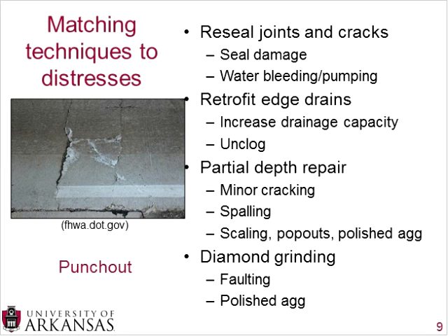And what can happen if you have those is the water bleeding and the pumping. Once those seals get damaged, water can go in and can come back out of those seals. And also material from the base and subbase can actually start moving up through those joints and cracks and cause more significant damage.